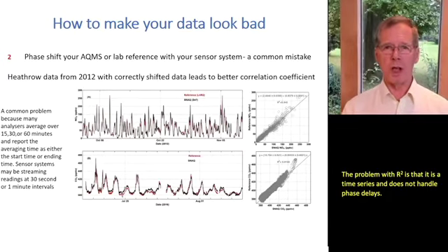Reference stations will average over a fixed period of 30 minutes, 15 minutes, 60, maybe even 24 hours, and will give you a single reading, whereas low-cost air quality networks frequently give out readings as fast as every 15 seconds or 1 minute.